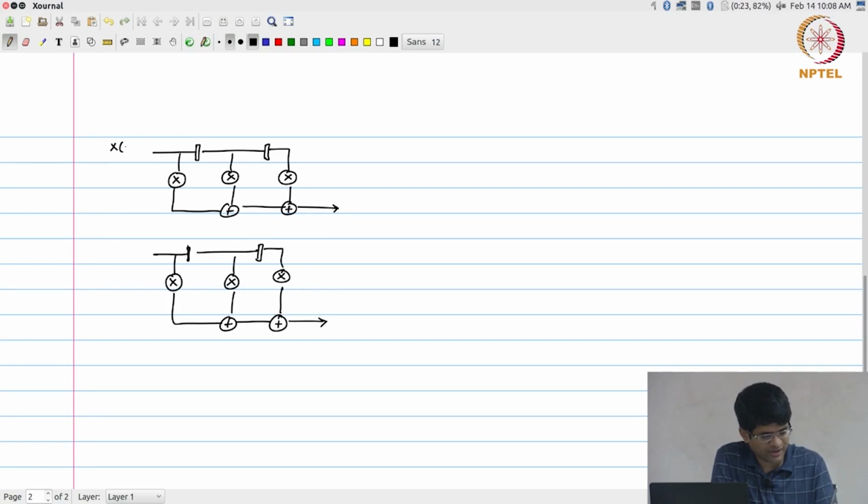So I have x of n feeding in here, and let's say I have x of n minus 1 feeding in here. Now what this architecture effectively means is, x of n minus 1 is also being produced over here, and x of n minus 2 is being produced over here. At this point it is x of n minus 2 and x of n minus 3.